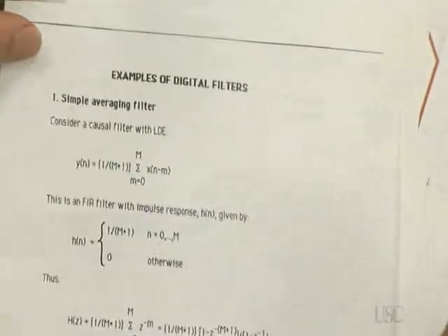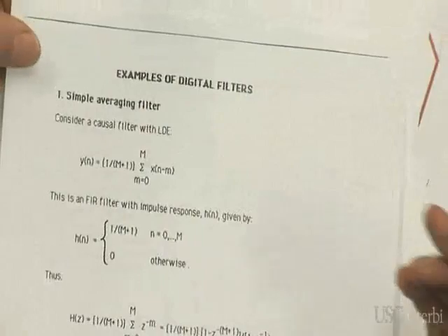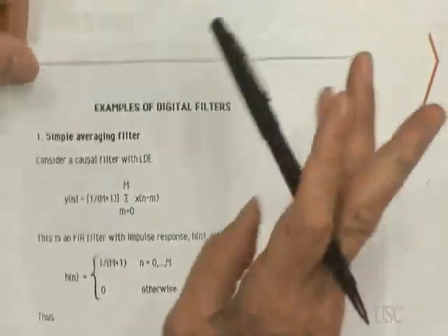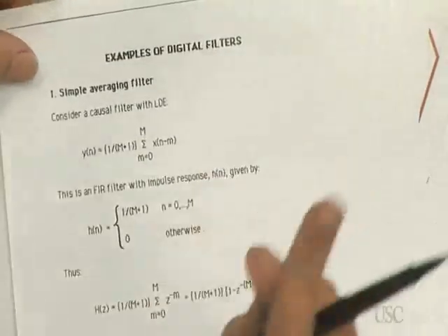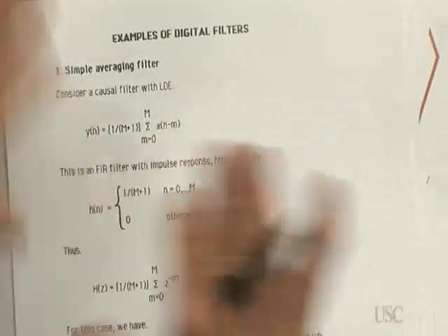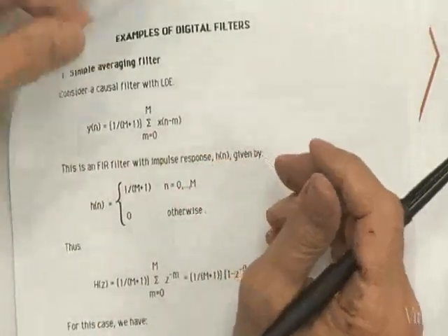So that is that. Now what I want to do, so that gives you an overview of Z transforms and the difference equations and how you can tell about the filters by studying the Z transforms. That's what I said. You're given a difference equation, you implement with a difference equation, but you analyze in the transform domain.